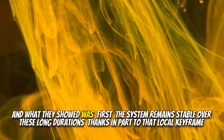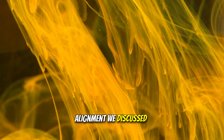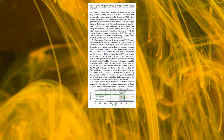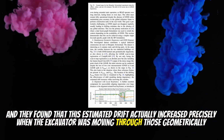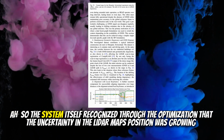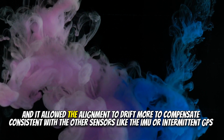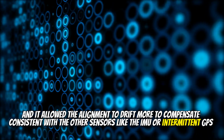Exactly. And what they showed was, first, the system remains stable over these long durations, thanks in part to that local keyframe alignment we discussed. And second, they looked at the estimated drift itself, the magnitude of the random walk corrections being applied to the LiDAR map's alignment. And they found that this estimated drift actually increased precisely when the excavator was moving through those geometrically degenerate areas where the LiDAR quality was expected to be worse. So the system itself recognized, through the optimization, that the uncertainty in the LiDAR map's position was growing, and it allowed the alignment to drift more to compensate, consistent with the other sensors like the IMU or intermittent GPS.